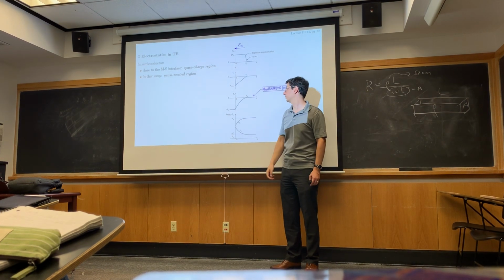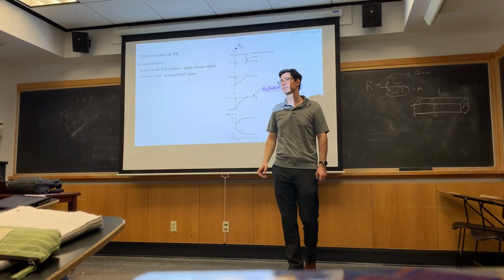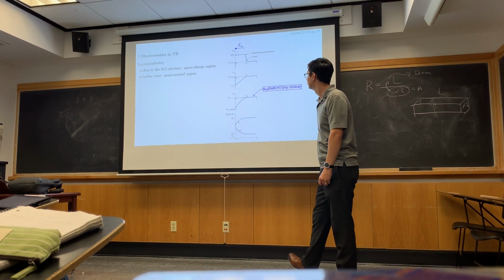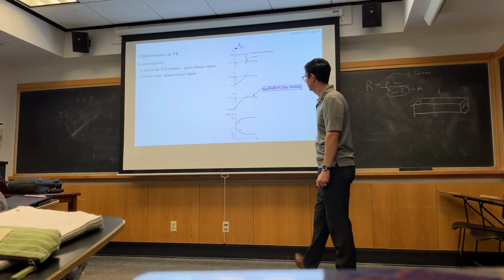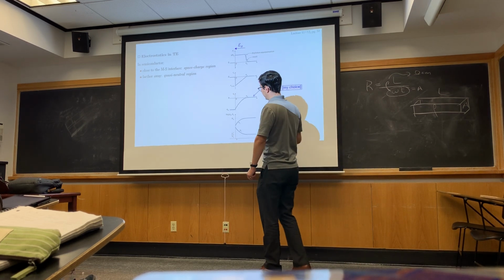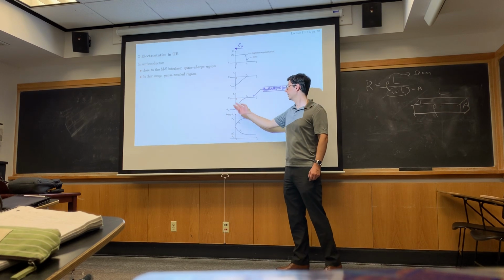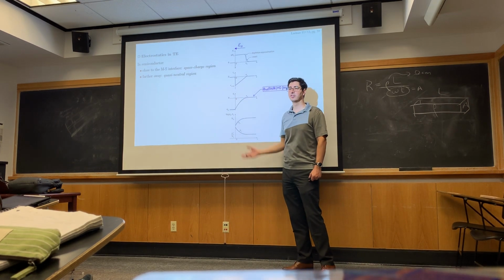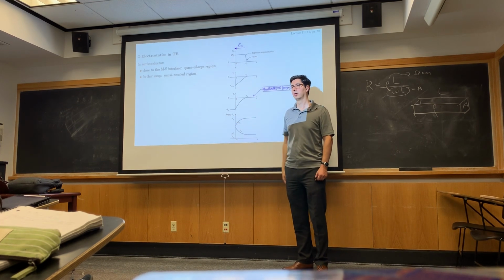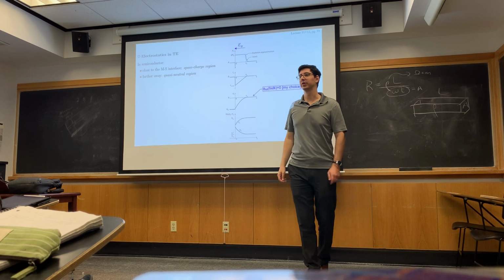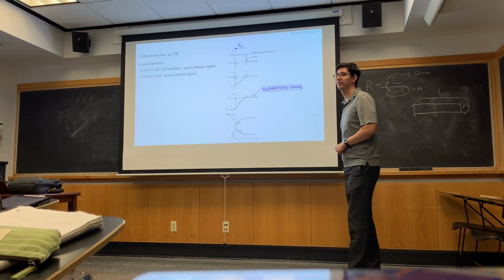In this case, minus phi bi if you follow the signs. And then from phi, I can draw my energy band diagrams. And from my energy band diagrams, I can draw p naught in it. And I'm putting that on the log scale, right, because they're changing very quickly.